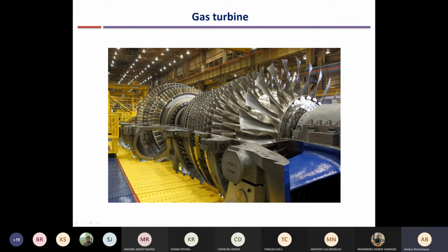Whereas what is happening in the turbine, the pressure is decreasing, right, from the upstream side to the downstream side, and the flow is actually going along the pressure gradient, not against the pressure gradient. So flow is going in a direction in which the pressure is decreasing. As a result, it is a favorable pressure gradient. So even if we have a larger pressure drop, then also because the pressure gradient is favorable, there is less chances of flow separation, and each stage can be designed with a much larger pressure ratio. Okay, so this pressure ratio which is generated typically depends on the blade profile, as we will see later.